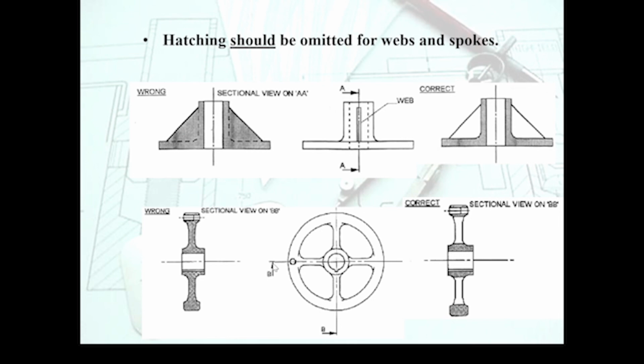So this time our cutting plane is not a straight line. It is actually a revolved view here, where part of the cutting plane is looking this way and the other part is looking that way, because there is no way of carrying on with this line straight in this direction. There is not much to demonstrate. However, there is a keyway this way, and hence the designer in this case decided to go from there and then change the direction. That is allowed. That is a perfectly good practice there.